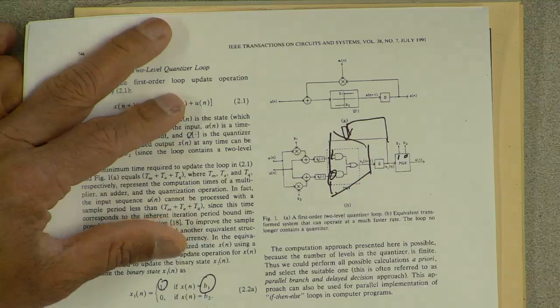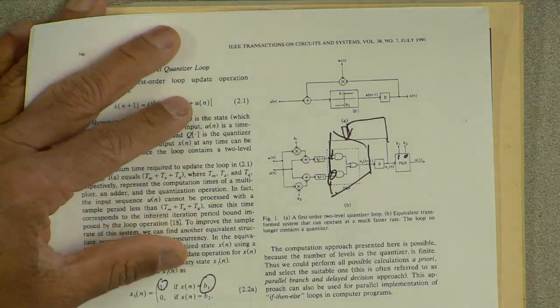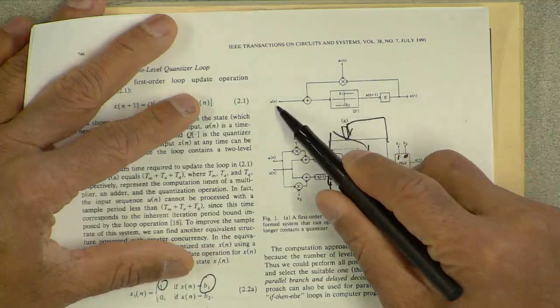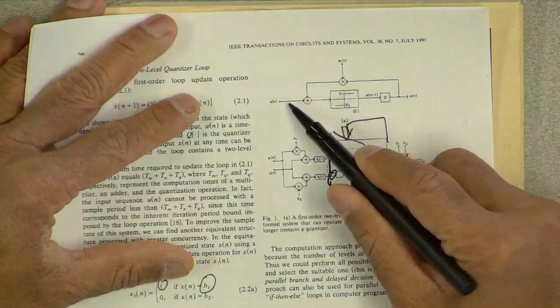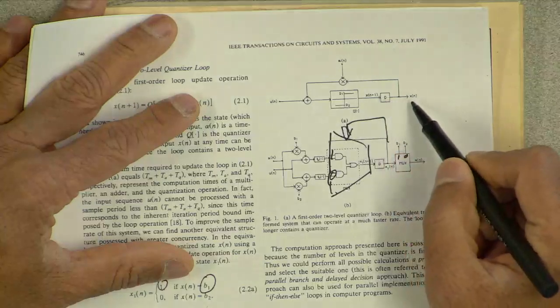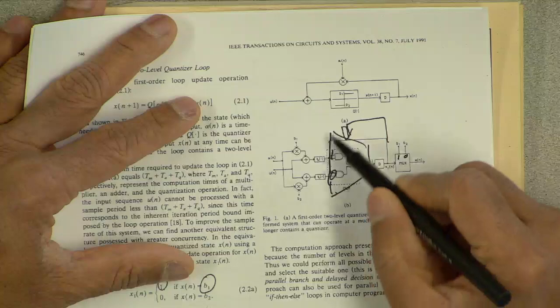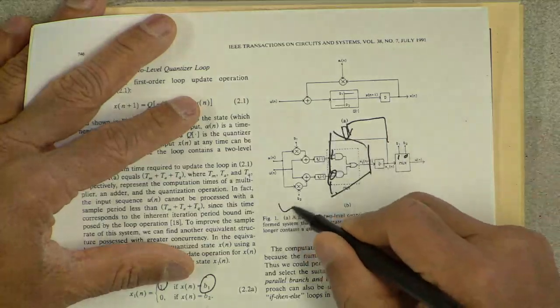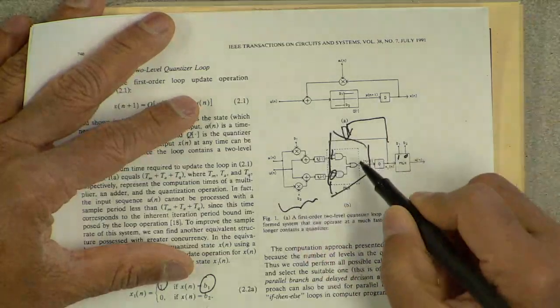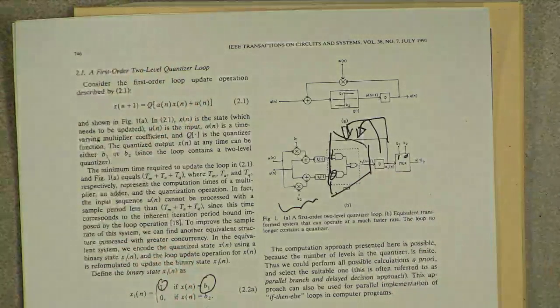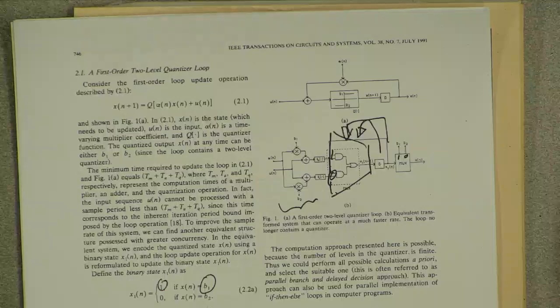So what we have been able to accomplish by pre-computing alpha n times B1 plus UN and quantizing that, and alpha n times B2 plus UN and quantizing that outside the feedback loop as a part of the pre-computation part, is that the iteration bound, or the loop bound, is now only the time to compute a 2-to-1 multiplexer.